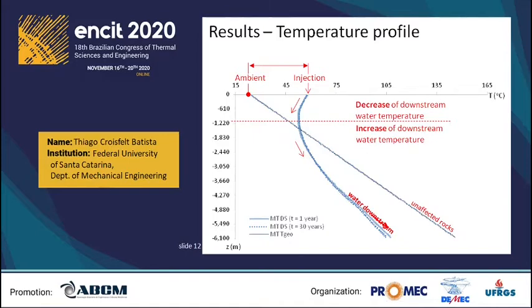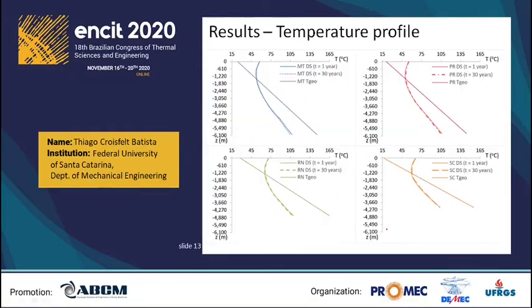There are some constraints in the power cycle related to the pinch point temperature that make it impossible to re-inject water at a lower temperature, which results in an unused exergy that's dissipated to the top layers of the soil and then to the atmosphere. This behavior happens in all case studies.